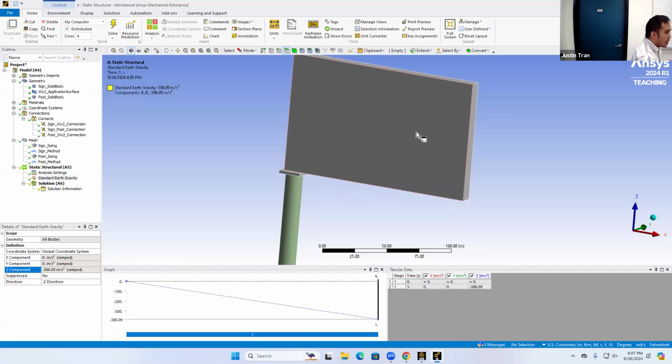Okay. Because a lot of times when you assign a very large force to a point, what that does is that it concentrates all that force onto a small point in the model, which can cause some stability issues. Okay, so I'm not showing you this because it's a best practices thing to do. I'm just showing you this to show that you can apply forces at a point.